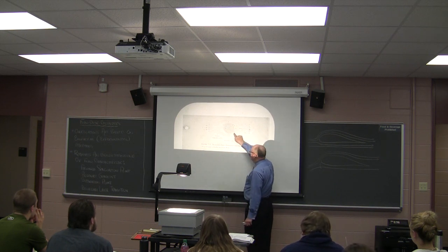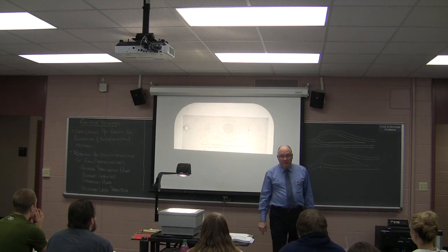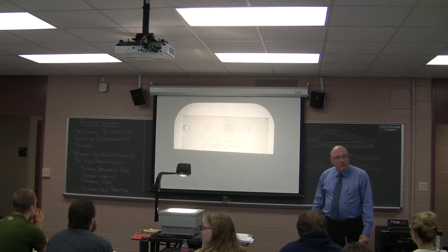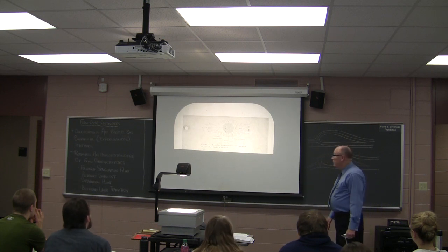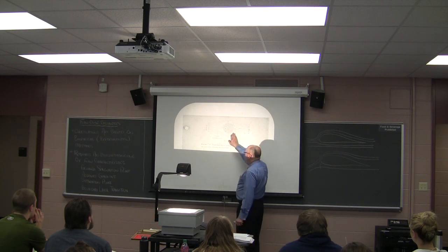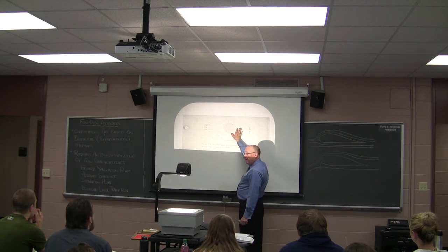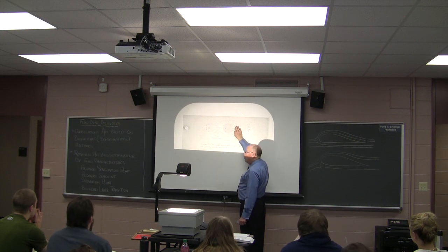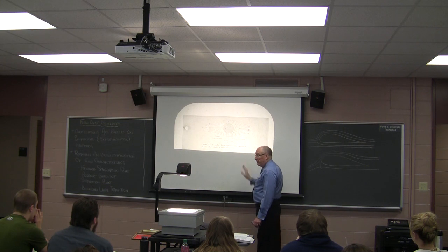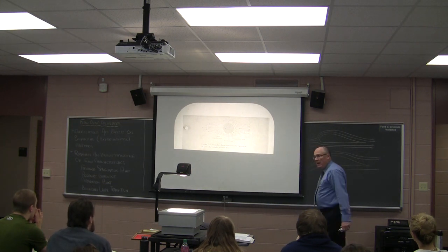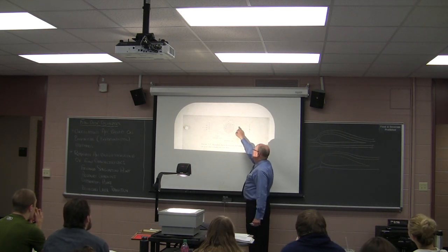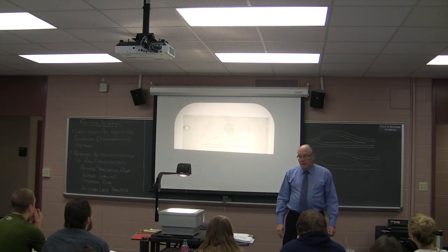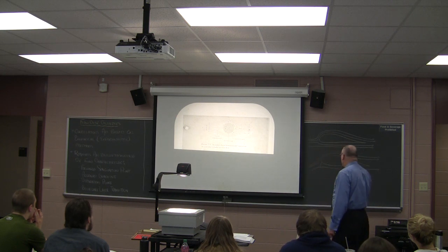Now, at some point, what happens to the boundary layer? Turbulence. It begins to unadhere from the surface. There's not enough energy in the flow to keep it following the contour of the cylinder. And so you get a pressure differential here, and we'll talk about that in a moment. And you end up with flow coming back in here and creating turbulence. And at that point, the boundary layer is separated.